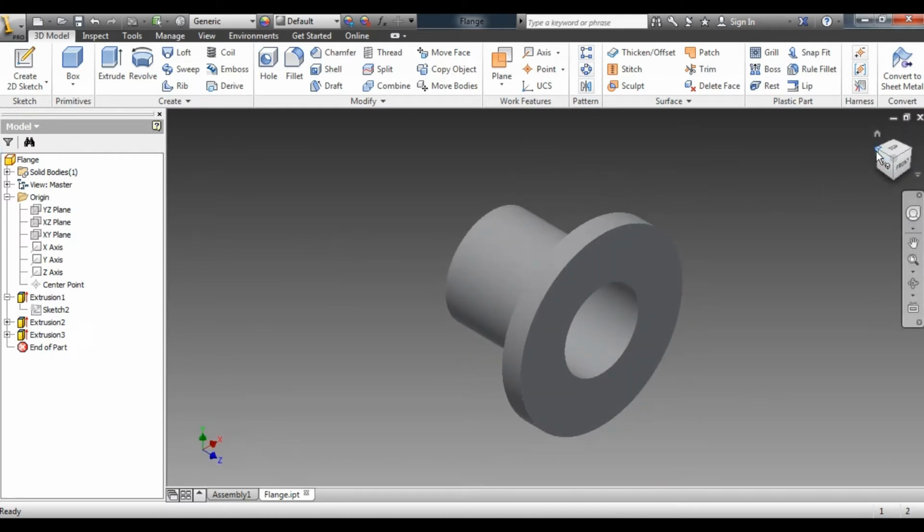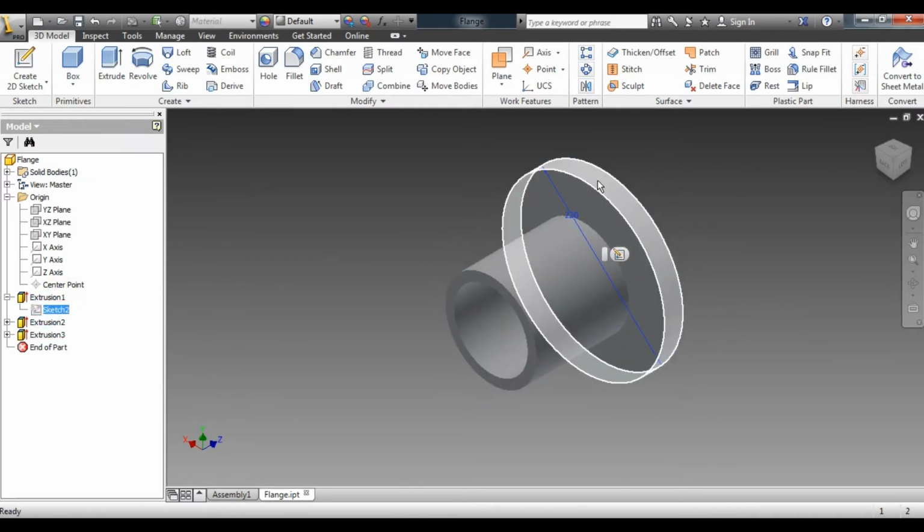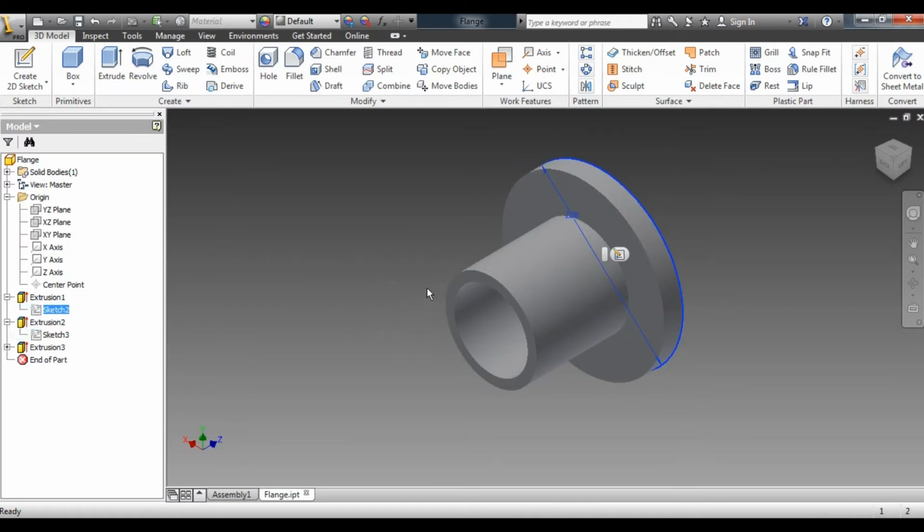Now you can see that in a side view, this sketch indicates the extrusion, the first command. Second, we drew the outer one, so that is a sketch, and third is this one. So this is the order of the commands. Each sketch and each 3D command is applicable. For example, if you want to change the outer one, I have to go to only the sketch command.